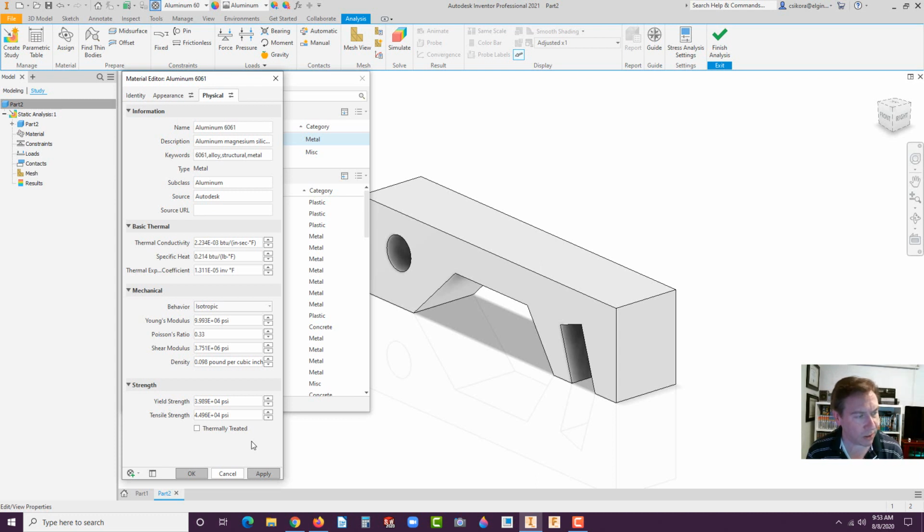You could actually do the conversions, like PSI into MPa, on Google and get that feedback on what that is. But typically, when it comes to yield strength for 6061, if you're talking MPa, it's between 100 and 130, or 125, I believe, without doing the hand calculation. If you're talking 6061-T6, for example, that's considerably higher. That's 275 megapascals. That's its limit.